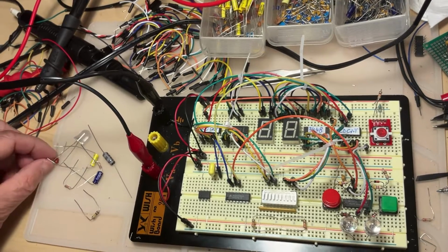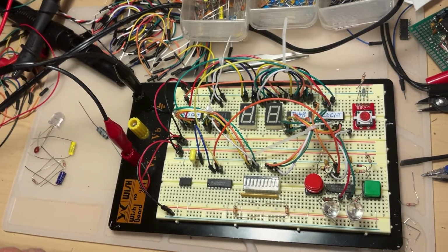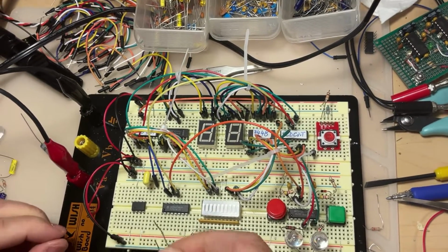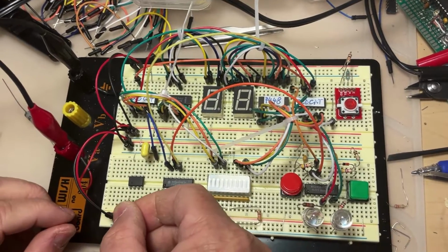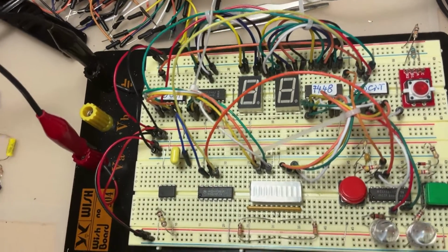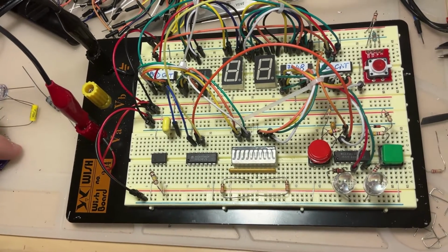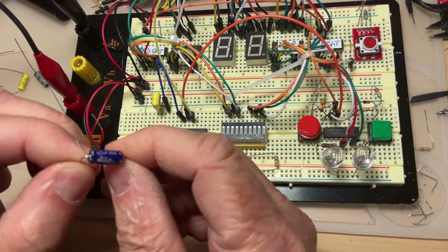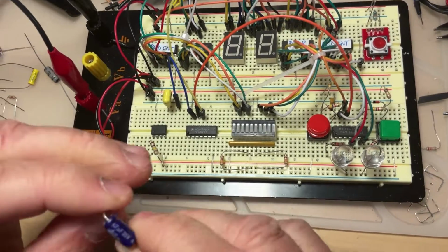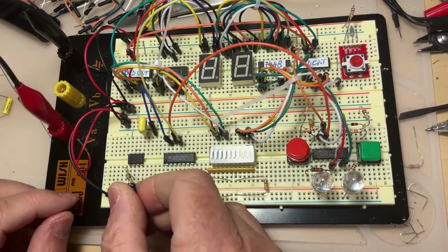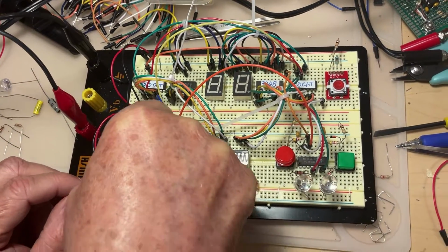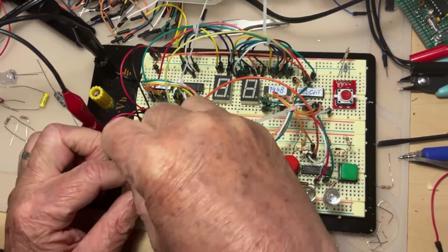So I'm going to connect this one to the triggering, which is the pin 2. I'm going to put here a capacitor. It doesn't matter if it's not a tantalum one, because whether it has a leakage or not won't matter. It's just to trigger, it's nothing else. This one is going to be connected over here, the pin number 2.